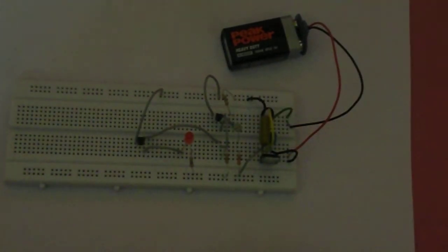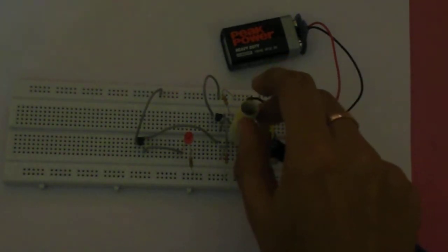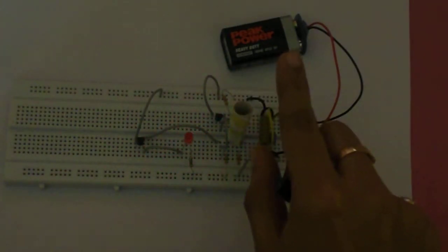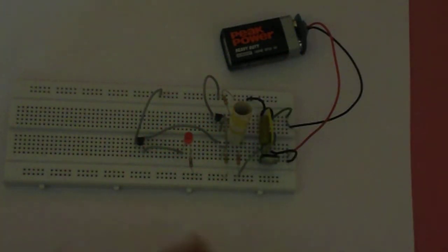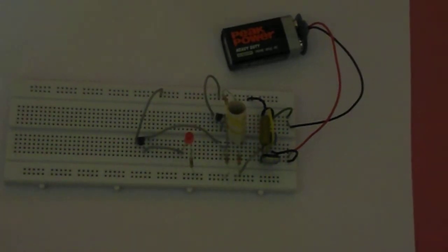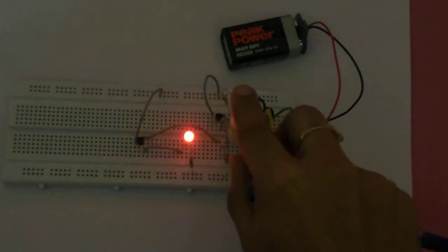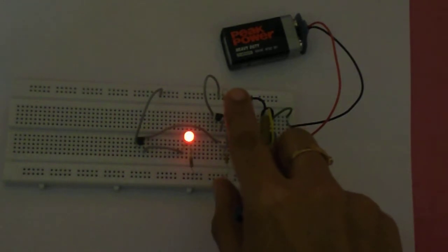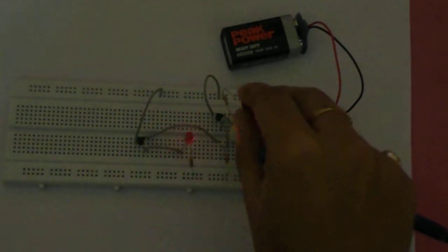So even if there is light, current flows through it, but only about 1.5 milliamps of current flows through it, and the voltage is not enough to cross the VBE threshold level of the BC547 transistor. But when it's dark, about 15 milliamps of current flows through it, around 10 times the current. So the transistor's VBE crosses the threshold level, and it saturates and becomes on state. So this is what it is.